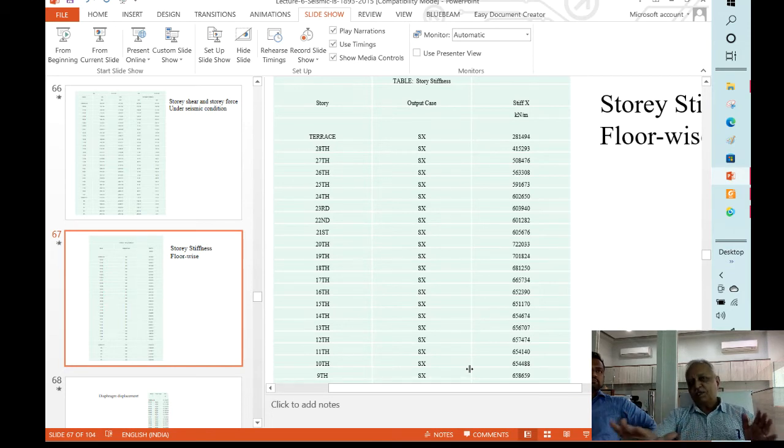So you have got some seismic force, some seismic moment. If it is a soft story, then you increase that seismic force. Don't increase dead load or live load, that is same. But your seismic force must be increased 2.5 times because of the local transition which is occurring. So there you have to apply the forces 2.5 times of the normal calculated as per the software. For soft story you increase it by that margin.